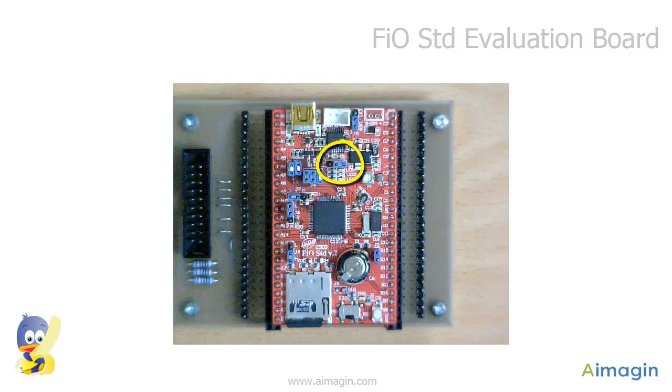This enables USB data lines. Jumper J1 must be both connected. This connects the USB data lines. Jumper J9 must be set to high. That's in low position. This allows the board to be set in USB in application programming mode. And finally, program switch must be set to the right. This will set the board to be in the programming mode.